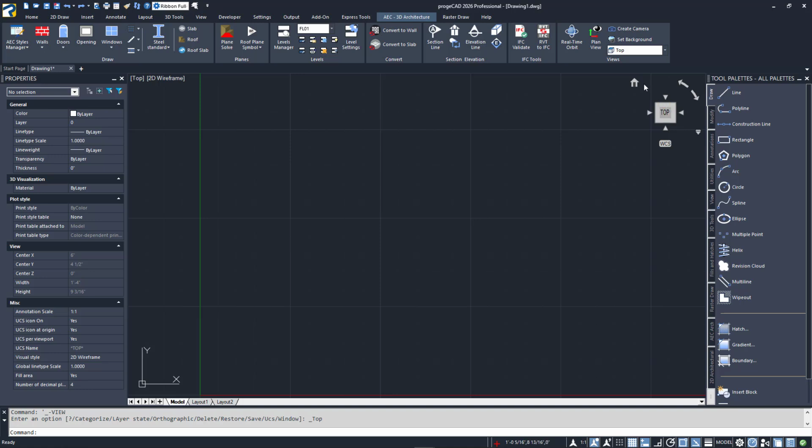The icon at the bottom that reads WCS allows quick access to any custom user coordinate systems you may have, or the orthographic projections as we saw in the viewport tools. The two curved arrows will rotate your view 90 degrees from the current Z-axis. And finally, in the middle, the cube has arrows around the edges which provide quick access to the back, front, and sides. When you click on the main tile of each side, you'll go right to that view. Finally, each corner of the cube is a shortcut to view your model in the corresponding isometric projection. I'll click on the southwest isometric corner to duplicate what we saw using the viewport controls.